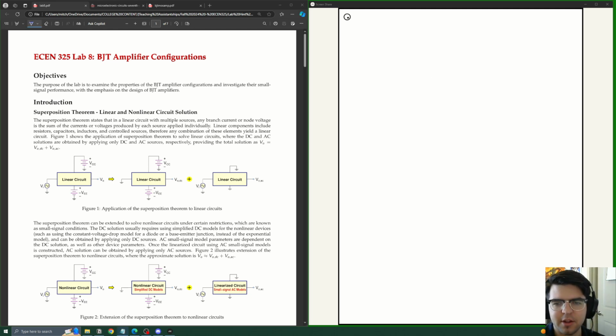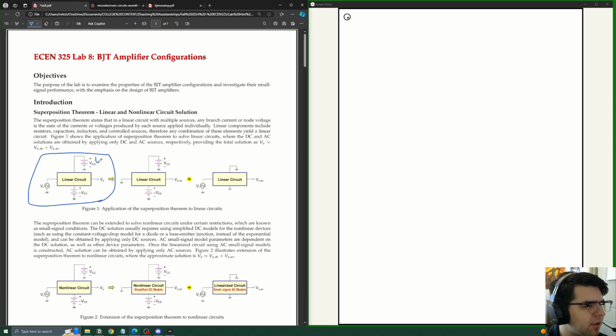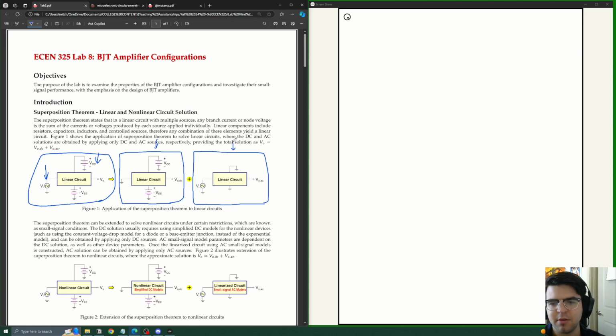So how do we actually analyze these transistor amplifiers? Because there's a whole lot going on. We're supplying power, we're supplying our input signal, and we've got all these different effects going on. Well, like before, when we were doing a lot of complicated analysis where there are lots of different power supplies, we applied superposition. It allows us to take this complicated circuit that has DC parts and AC parts and split it up: let's look at what the DC bias does on its own, and then let's look at what happens to the AC signal that goes in. Let's just look at these two things separately.